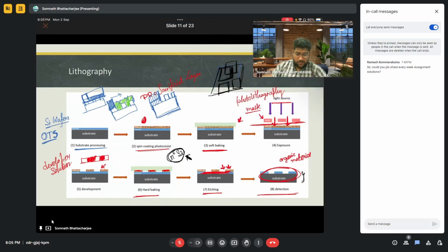And for the multi-level lithography process, as I was already telling you, there will be multiple levels of optimization as well. Even if you optimize the first layer of the lithography, for optimizing the second layer you will require many more information for that. So you need the information for that level, and also to maintain a stable first layer. You will need to understand the physics of the first layer and the second layer both at the same time. So you can understand if you are having, let's say, 11 levels or 12 levels of photolithography, you will need to understand the physics for all the layers.